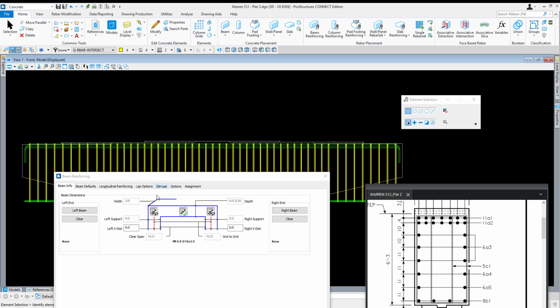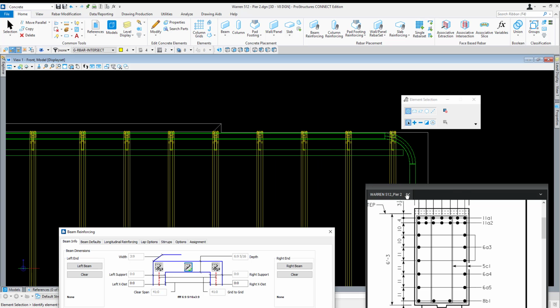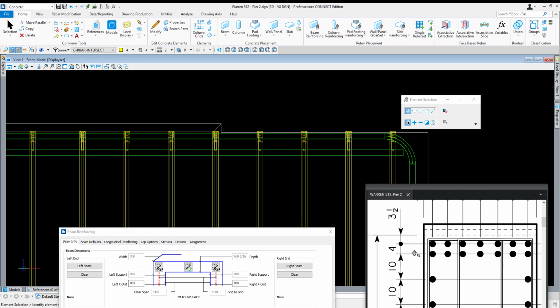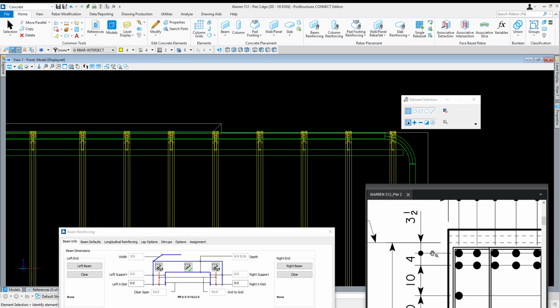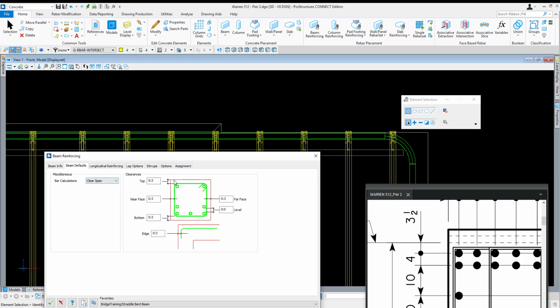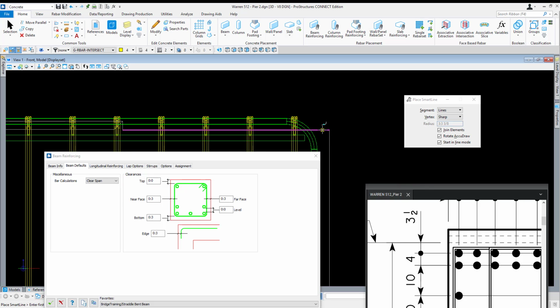So after selecting the beam, I can see it's utilizing, I guess, the greatest possible geometry available, and I need to make some adjustments to get these bars to be where they need to be, as shown on this drawing here. So I need 3.5 inches to center line of top bar from the lowest point. So currently, if I go to my beam defaults tab, what I'm going to do for my top is just zero it out. Then there's no question about how far down I need to go. So I'm going to set my origin.